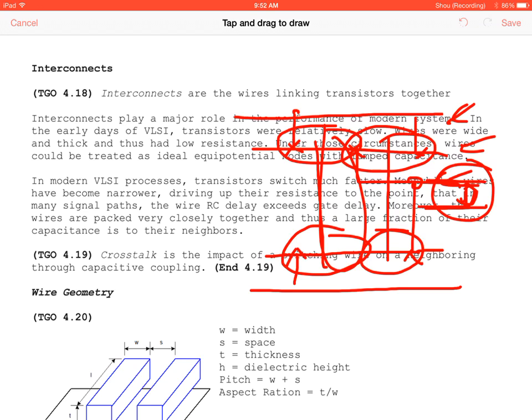So what do you have between your wires? A magnetic field? Well, it will create a magnetic field, but specifically you have one charge carrier and another charge carrier, and they're separated by a width. What does that create? It creates capacitance, right? So as you get these wires closer together, especially as feature size goes down, you have to worry about capacitance.